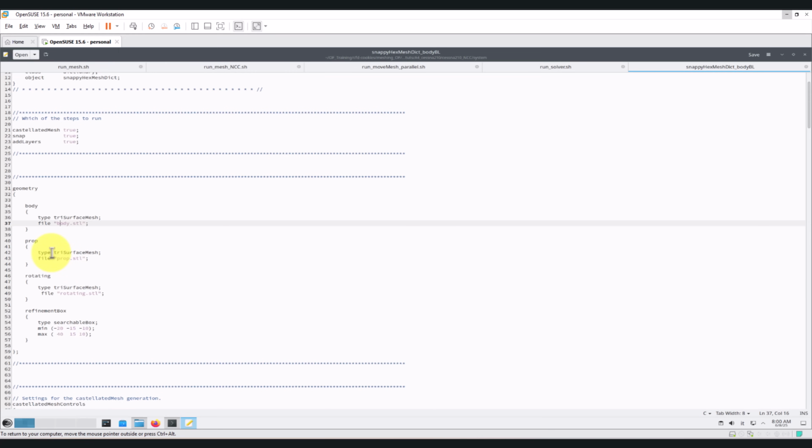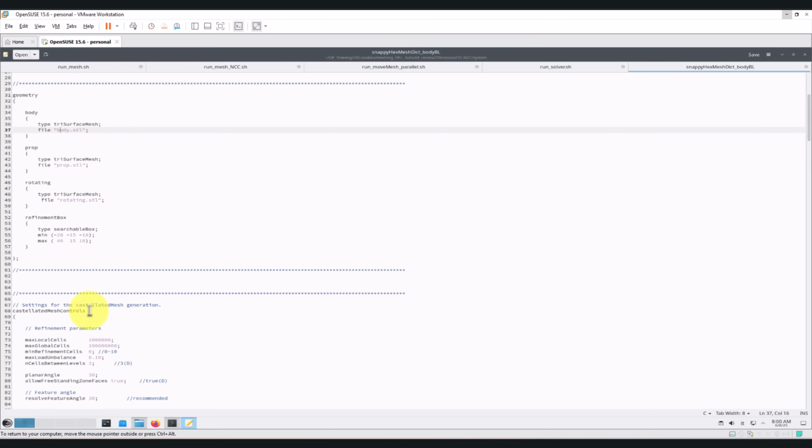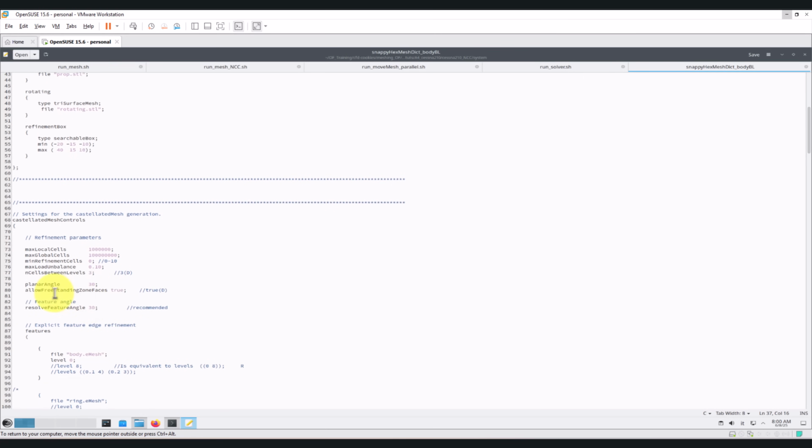We're just seeing the simplest option, the ones that you are going to use most of the time, but you have different keywords there, but I don't want to comment on that. Then we move to castellation, which is the Cartesian mesh. We do all the cell addition here. Then also there is some old cell addition in the boundary layer, but all the cell addition for the surfaces, edges, and regions, volume regions is done here.